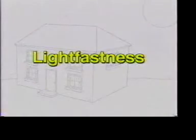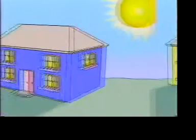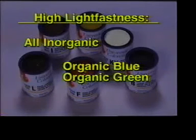Another area of difference between organic and inorganic pigments is color permanence or light fastness. Light fastness is simply a measure of how quickly, if at all, colors fade over time from exposure to the sun's ultraviolet radiation. Colors that resist fading caused by ultraviolet light are said to have a higher degree of light fastness. Inorganic colorants, as well as the organic colorants of blue and green, have fairly uniform high levels of color permanence or light fastness.